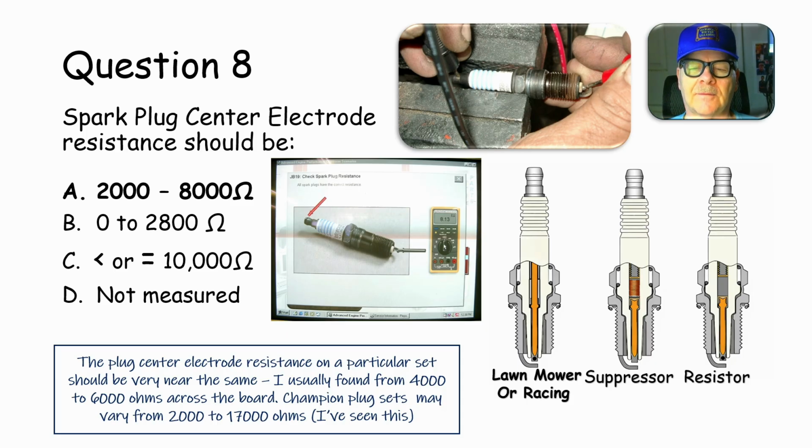And so there was a transmission mechanic named Mickey that was across the shop while we were talking. And Mickey says, hey, they brought this in for a transmission problem, and it's got a misfire. And I looked, and it was one of those Explorers. I said, put a number 4 spark plug in it. He said, okay. And so he went and got a number 4 spark plug put in it while Donnie and I were still arguing about that. And when he got through, he hollered back over. He said, that fixed it.